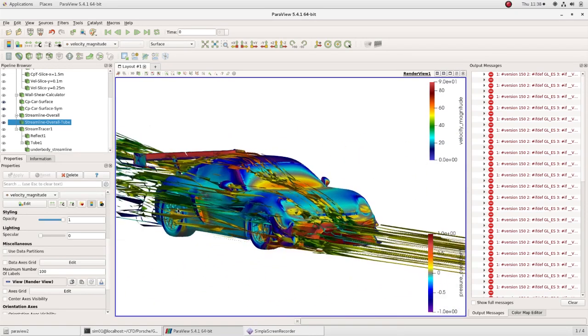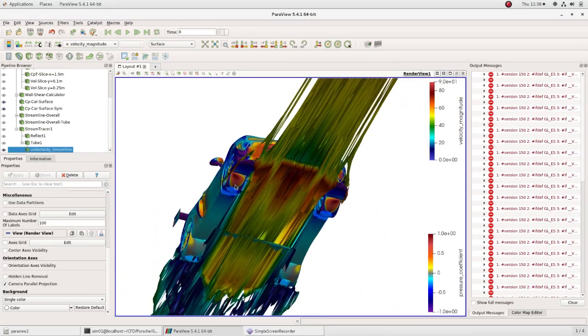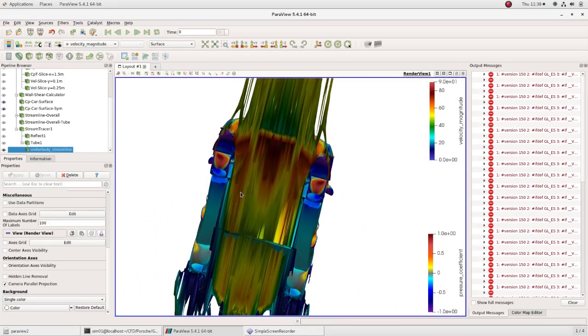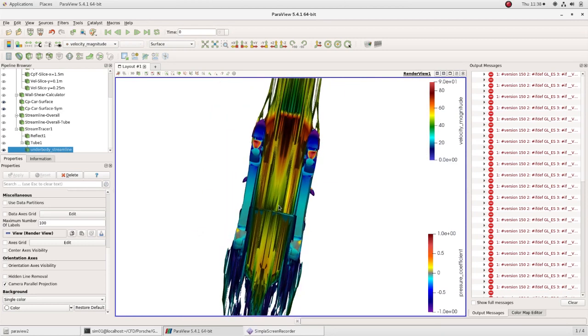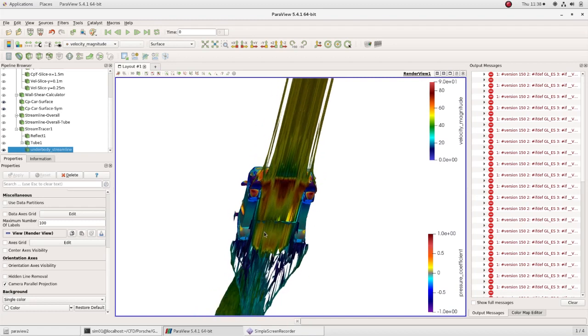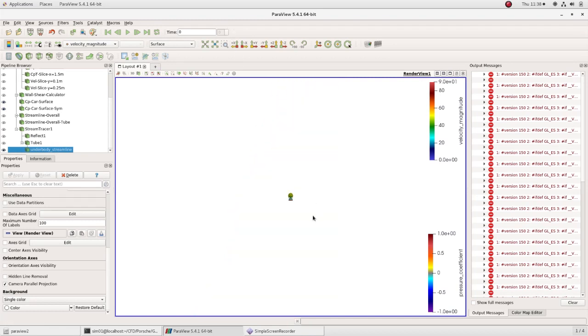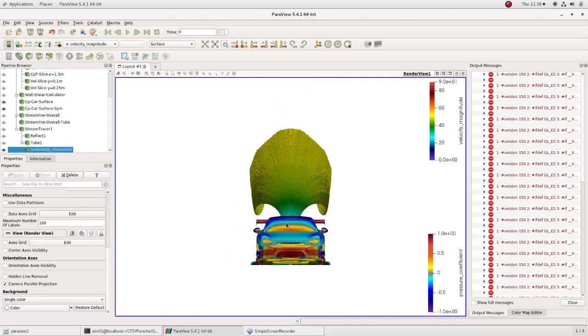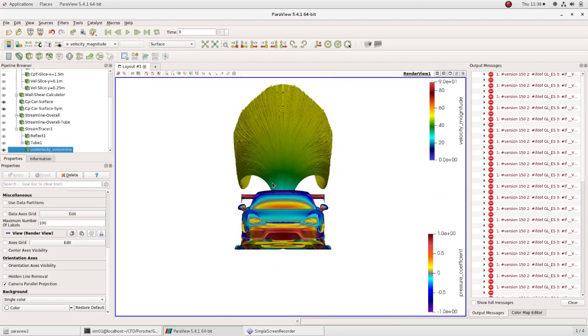The underbody streamlines are a great way to see how the underside of the car affects the air it's dissipating. Dirty air off the rear tire can easily be seen here. The height at which the streamlines go behind the car is very impressive. This shows how well the rear diffuser and rear wing are working together.